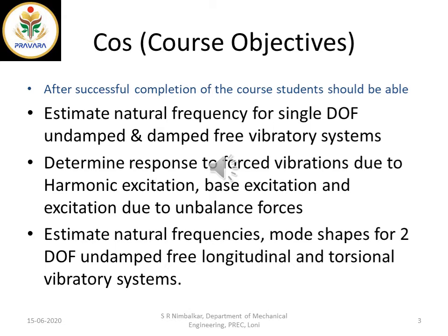So the first is to estimate the natural frequency of single degree of freedom undamped and damped free vibratory systems. Now this is an important concept in vibrations: natural frequency. This natural frequency is restricted to single degree of freedom. We all know the degrees of freedom from TOM, theory of machines, which you already studied. Degree of freedom is related to how many variables you require to describe the system. So if you require one, then it is single degree of freedom.